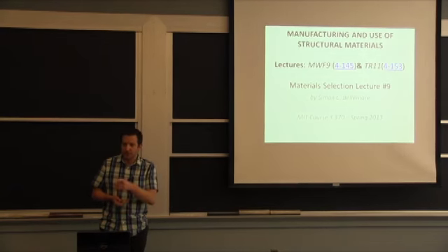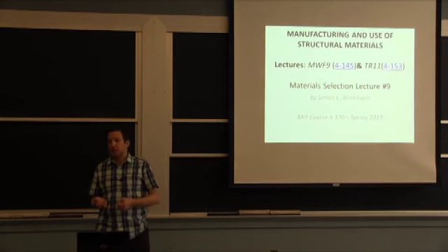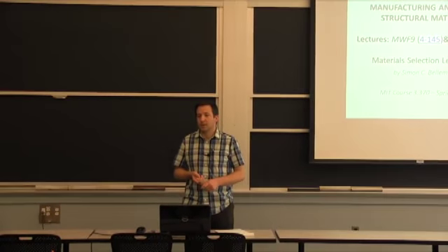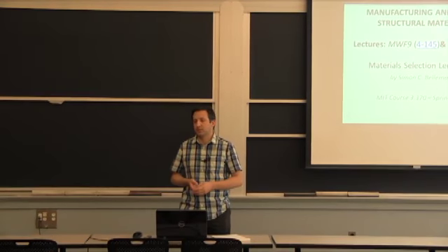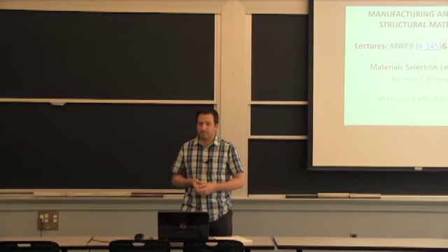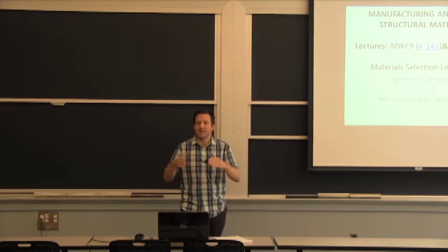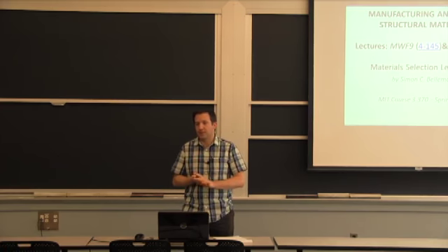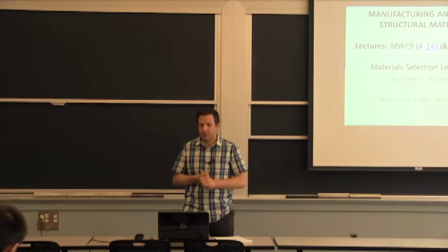So this specific component just went through a beating because we know it suffered creep damage, because it formed an S shape on the blade itself. We call these a cluster when you have more than one holding together. It suffered this form of microstructural attack. I don't know the details of it, but we can see cracks that are extending beyond the area that was shattered. So the whole microstructure became brittle, and that's how you had cracking and a premature failure.